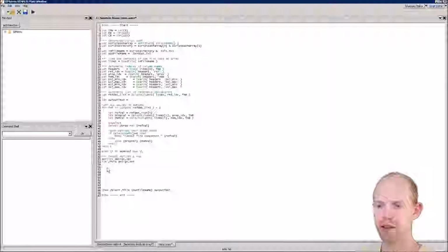Now the next thing here is getting the parameter. So let's make a nominal parameter variable, and to get the rise time we're going to get x from y of vout, which is our node name, and we're going to get it at 5 volts minus at 1 volt. So that'll be the time distance from 1 to 5 volts.